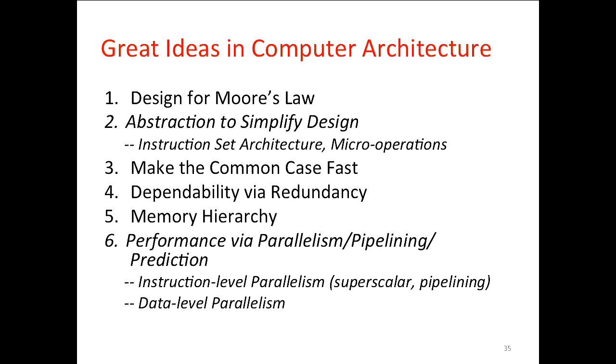Right? So, down at the core level, this idea of abstraction, we write, in this example, x86 assembly code that gets turned into machine code. And that's the interface between software and hardware. However, as we saw in this chip, the story doesn't really end there because the hardware takes that x86 assembly code and actually turns it into something else internally. So inside the chip, it's breaking it up into something that looks like those RISC instructions you've been using in MIPS. Executes those, but completes them and commits them so it looks like it did those x86 instructions on the outside. So that's the idea of abstraction. We hide the fact that all this stuff is going on and make it look like an x86 on the outside because that's what all the software expects on the outside.